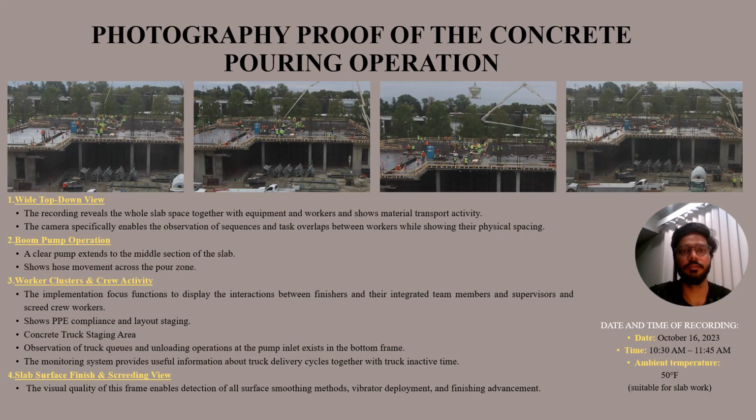Now we have attached some photography of a concrete pouring operation, which we observed through a web camera. As we can see on the right-hand side, we observed on October 16, 2023 from 10:30 to 11:45 am, and the temperature was 50 degrees Fahrenheit, which is suitable for slab work. Talking about the wide top-down view, we can see the full layout of the slab, equipment and workers, which are sequenced, and overlap occurs between a few crews, as they were all working on the same slab.